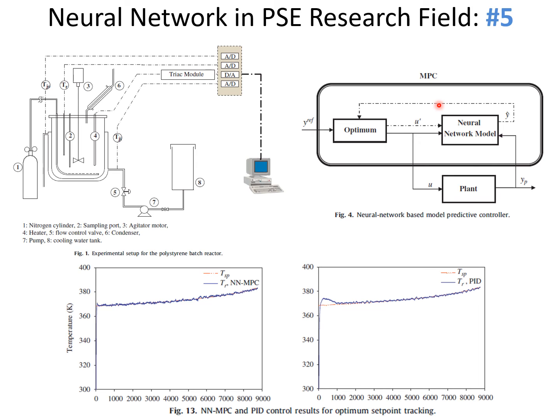We call it the receding horizon control method. The optimum is normally a profile because that gives a better result when we have a future profile than just one value. But the implementation normally is, of course, the next one. Then it goes again, so it's recurring, but we implement one. So this neural network based model predictive control, we use it to track this profile with noise, of course. Noise, because the real world is noisy.